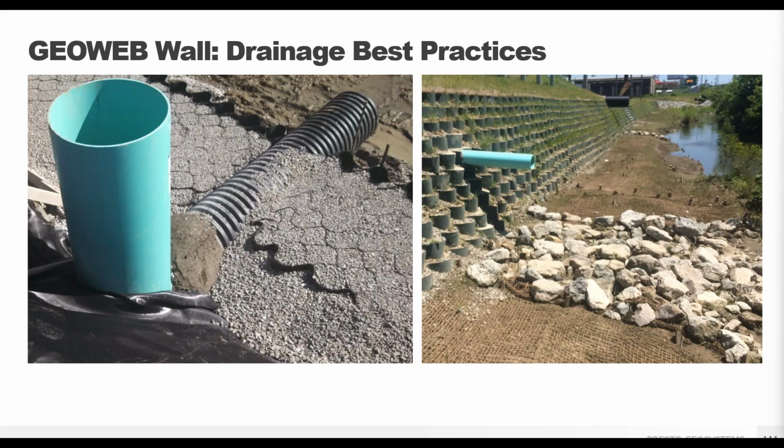The GeoWeb system is better equipped than impervious walls such as concrete block walls because by its nature, it allows for water movement throughout the system. However, even with this, it's crucial that you understand your specific site conditions and ensure that hydrostatic buildup is mitigated.